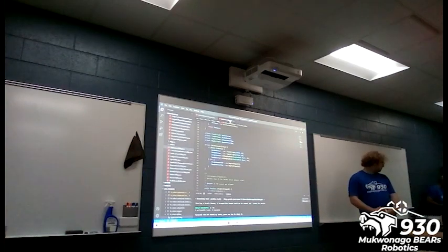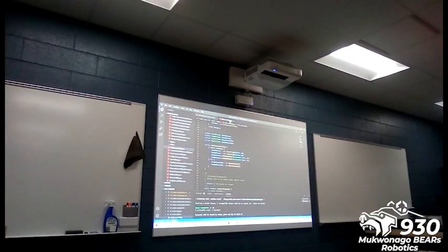So, first of all, this is how you get into simulation. You'll have to press the W in the top right of your WPILib to open the command bar. From there, you probably won't have it at the top of yours, so you can just type in sim, and then it should be one of the first three options. It'll build, and then it will give us a little selection. You can simulate your gyro station, but generally we'll just be using the GUI.